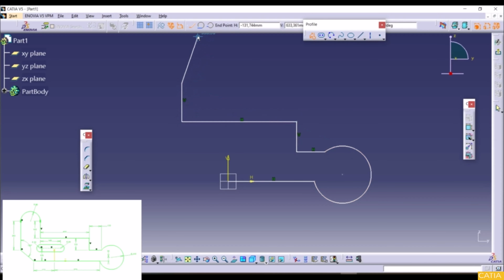And now we have to switch here to the tangent arc, and here we have a tangent arc. So make sure that you can see this horizontal tracking vector, like this. Let's go down. Let's go here with an angular line to this tracking vector, this one here, like this, that goes through the origin. And now let's finish here with a horizontal line right at the origin, like this. And this is our sketch contour.